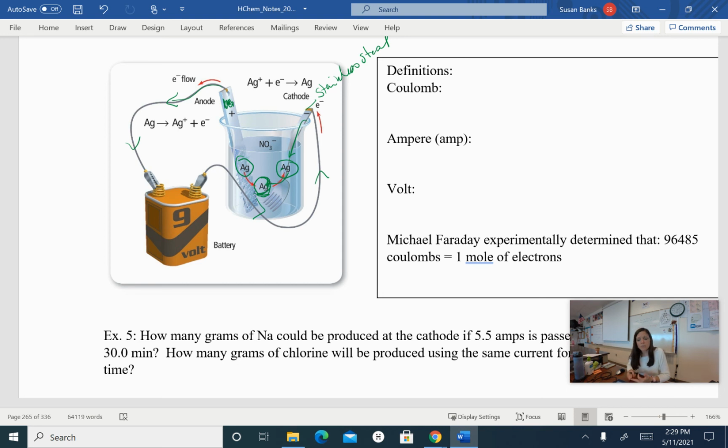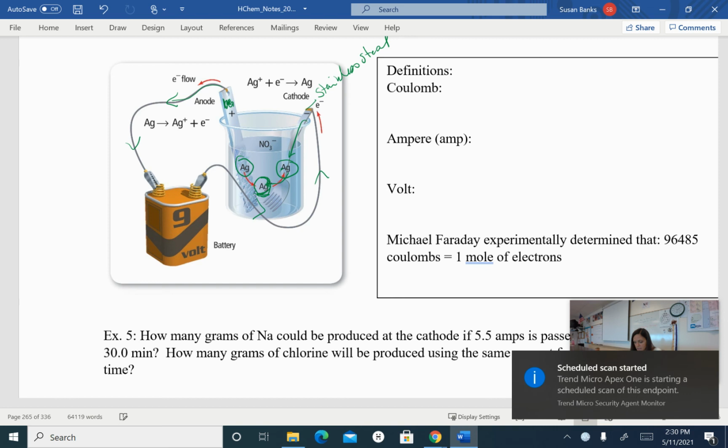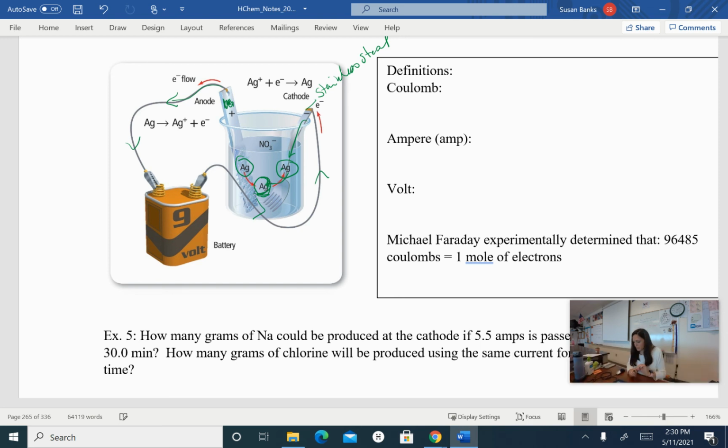Now that allows us to have silver, gold. Sometimes they use this with chrome. This allows us to have those finishes without making the whole object out of those precious metals. One, so that we're not using so much of the precious metals, so it's not nearly as expensive. And let's be honest, some of the precious metals like gold and silver are actually quite soft, and they are not durable enough to be knives and forks and spoons. They bend and they'd be soft. So that allows us to have a core of stainless steel that's a little bit more rigid, a little bit more tough, so it will last longer.